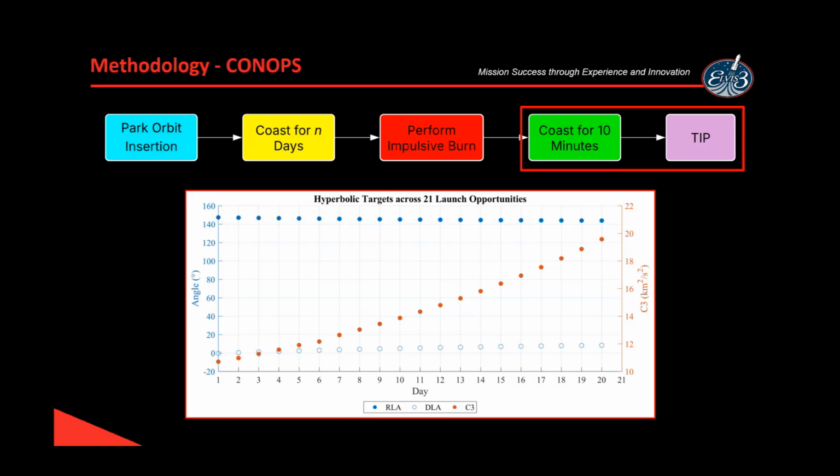So the next question, Justin, is, as you mentioned, modeling the ascent is critical in order to get an accurate picture of the real benefits of that optimal park orbit. But it's not just delta V alone, right? The loss of performance that you incur by ascending to the polar orbit of the same shape, let's say roughly 500 by 500 kilometers, results in a decreased payload to that orbit, assuming you were inserting that max payload at 28.5.